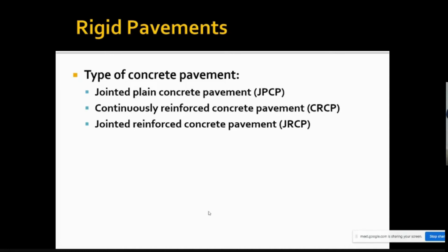So at ports, like seaports, the harbour by the sea, you will have so many containers, heavy lorries, trucks. Wait, my friend, I don't remember what grade it is, but I think it's 40 and above. That is the rigid pavement concrete mixture.